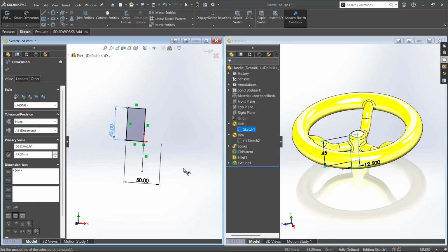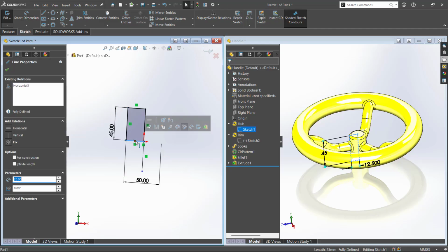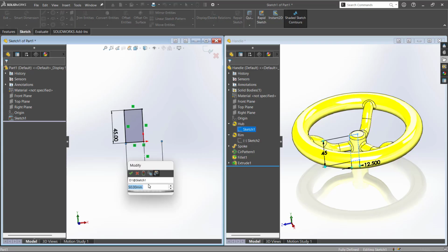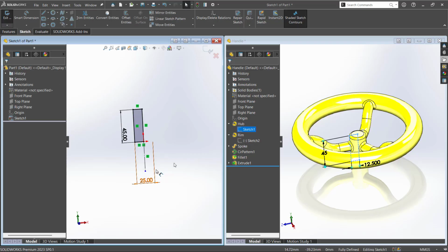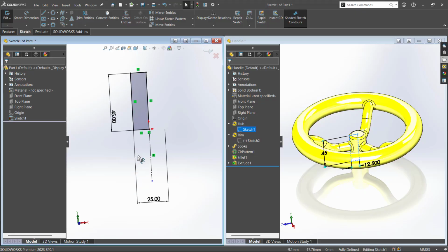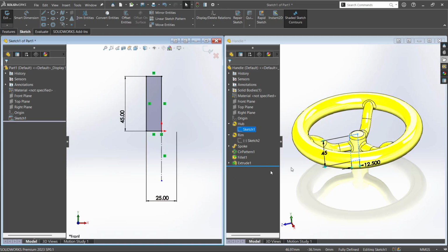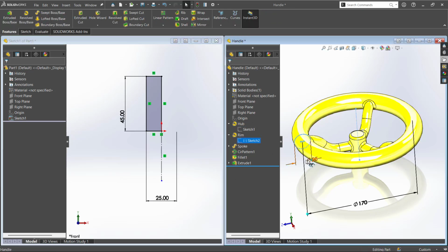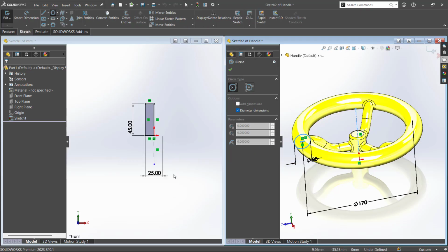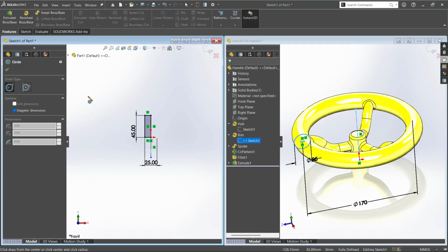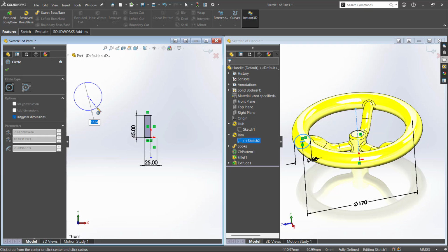There's no issue. If I try to measure this one, it shows 25. It's too much, since it should be 25 in short, right? Now it is 12.5. Perfect. Now in the same manner I'd like to draw this. It's just a diameter. I just need a circle. The circle should be somewhere in this region here. Let me do it. And the diameter is 25.